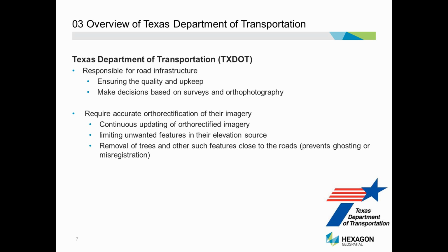They're continually updating the orthorectified imagery. They want to make sure that they have fresh imagery all the time. Limiting unwanted features in their elevation source: if you have unwanted features in the elevation source, you would want to remove those so that they don't interfere with the actual orthorectification procedure.